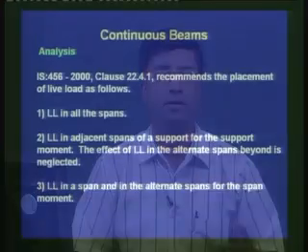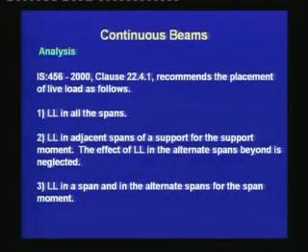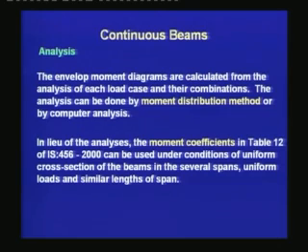Now, from all these load cases, we develop the envelope moment diagram. The envelope moment diagrams are calculated from the analysis of each load case and their combinations. The analysis can be done by the moment distribution method or by computer analysis. In lieu of the analysis, the moment coefficients in Table 12 of IS 456-2000 can be used under conditions of uniform cross section of the beams in the several spans, uniform loads and similar length of span.